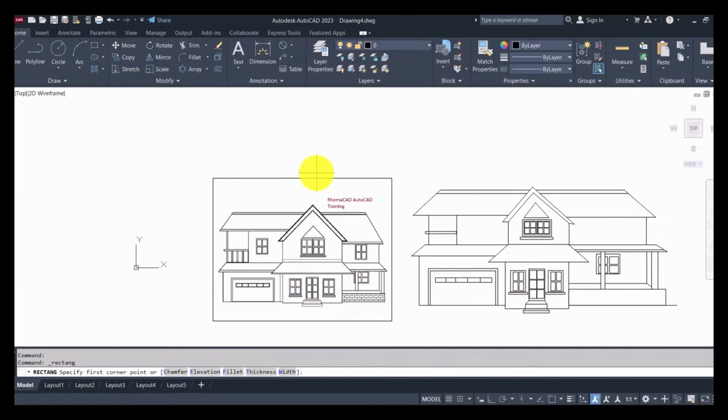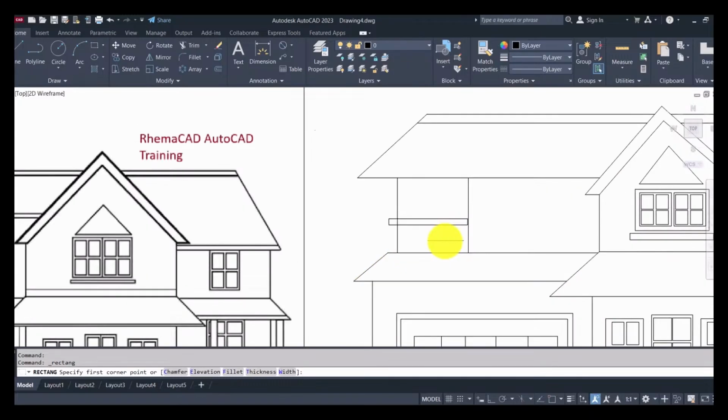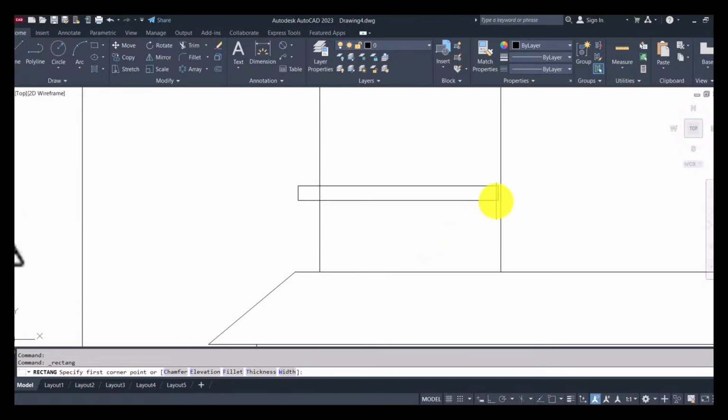And I want to zoom this region out so I can get details on what is over there. So I'm going to zoom out here. Okay, so zooming it out, I can see I might need to adjust this. Okay, so rectangle, 3 rectangles serving as my railing. So I can decide to draw one, then make copies of it.